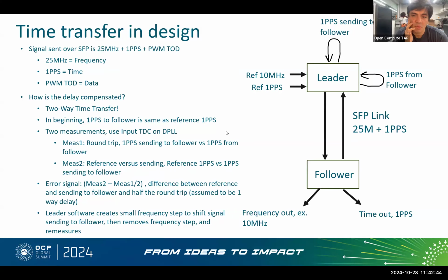I'm thinking about the scaling. You cannot do broadcast, so you need to go back because you want the compensation of the latency. I guess in that respect, it is different from Ethernet too. There's no concept of frames really. It's just a clock with stuff in it. So there's no way to do a broadcast packet or something. Every packet, time of day or FIFO, is over a dedicated link. Yeah, it's all point to point basically.